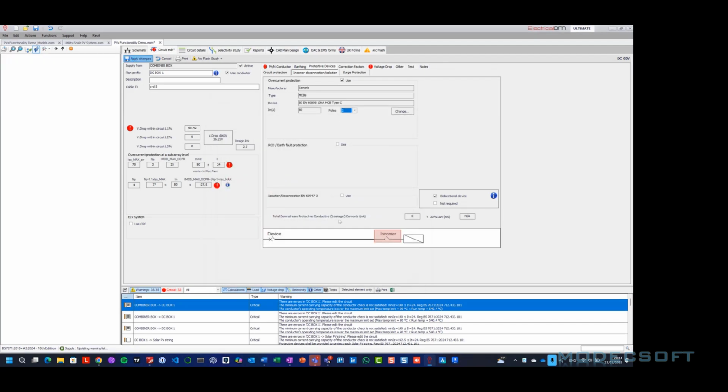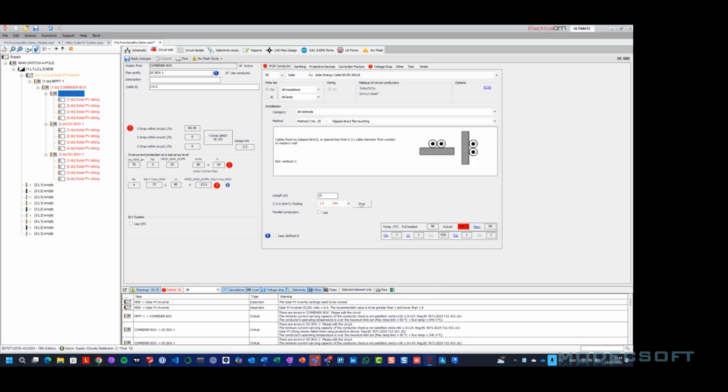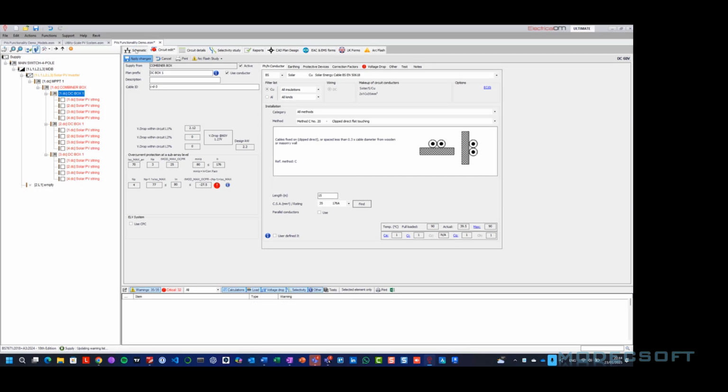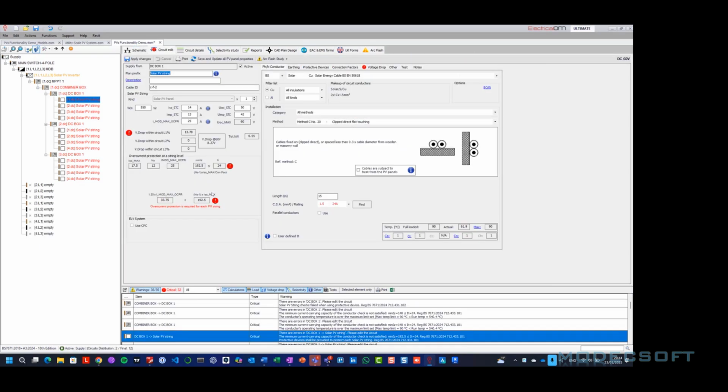By the change, we still have to deal with the problem related to the PV strings. Very quickly, we can access any of these PV strings. And to deal with this problem, either we have to enable power optimizers to restrict any reverse currents in our PV modules, or we can enable circuit protection for each of these strings here.